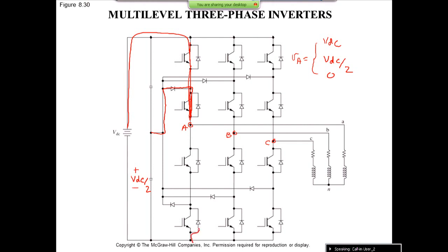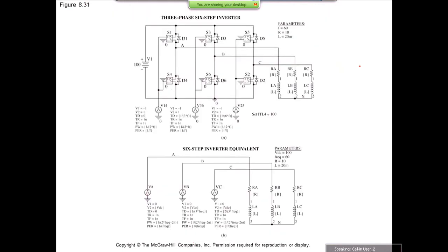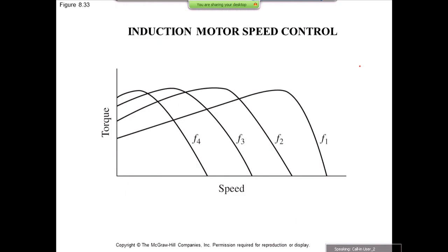And that is when we have a short circuit path here and here, for instance, through the diode. So now you can acquire 3 levels for your A to ground. Before we couldn't actually create this one. So now that you have more levels, the indication is the resolution of your output voltage is going to be better and total harmonic distortion is going to be better. But I don't really see any results over here.